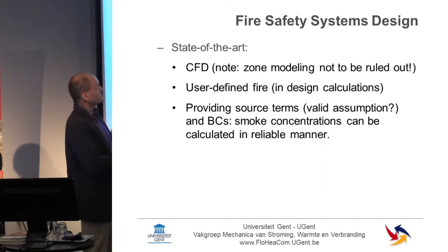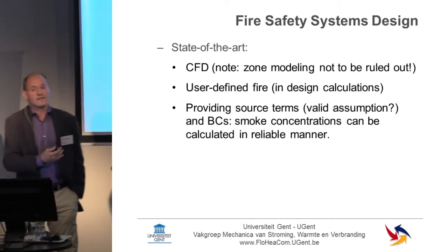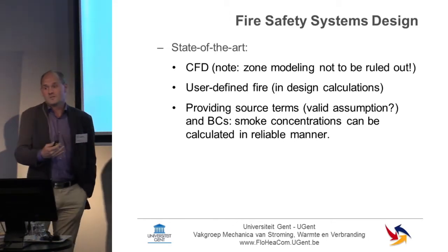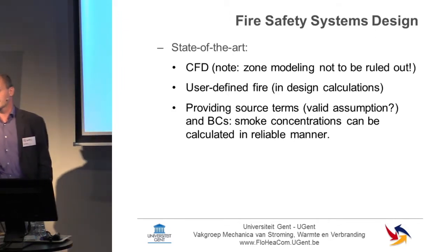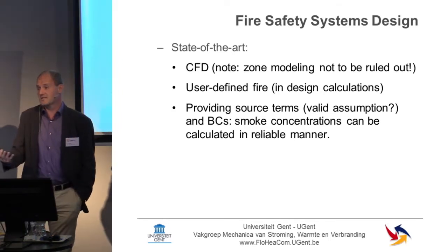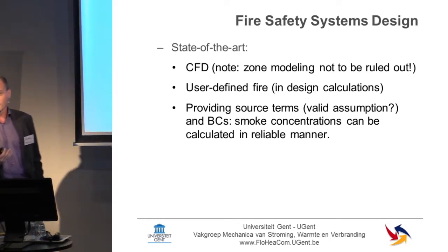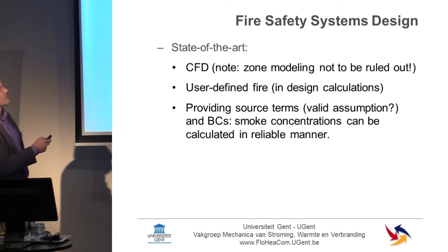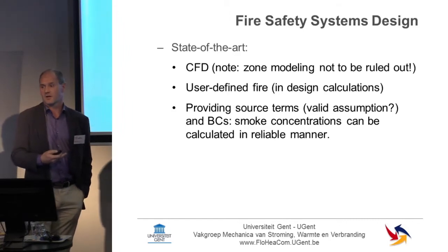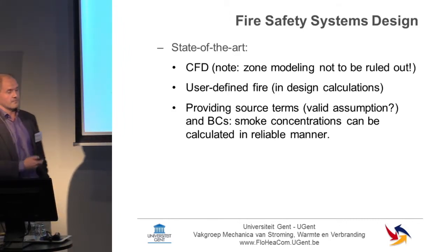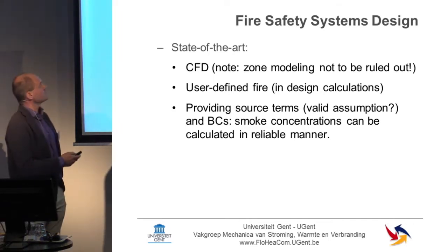I don't think it's useful to try to calculate a developing fire from the very beginning in the context of design, for the very simple reason that a design serves to ensure fire safety for a building that has not been finished yet. It's impossible to know what exactly will happen if there's a fire, what the fire conditions will be, what the weather conditions will be. So for the time being, we will have to use user-defined fire. So the calculator will decide beforehand which fire design will be calculated.